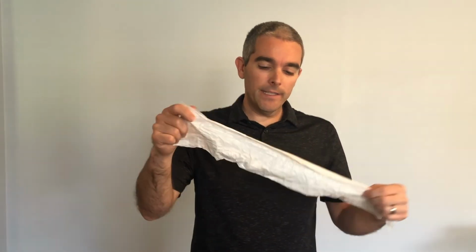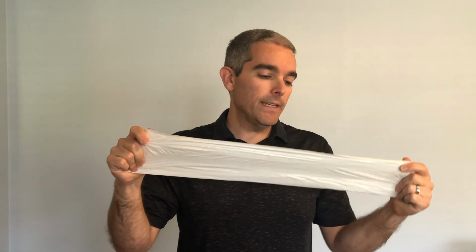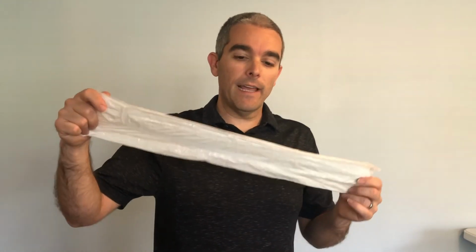We're concerned about yielding in the gross section because over the entire member, if the entire member is stretching, that's the yield strain, but it's multiplied by the entire length of the member.